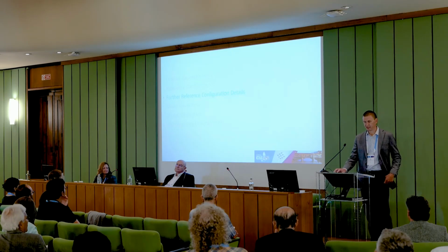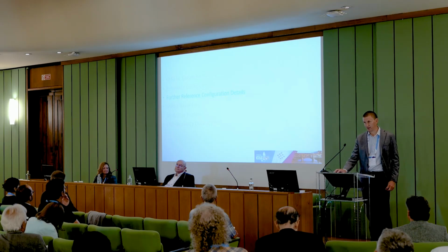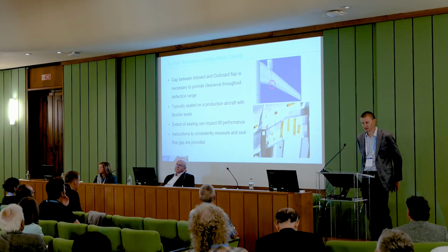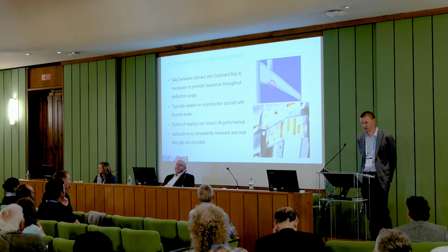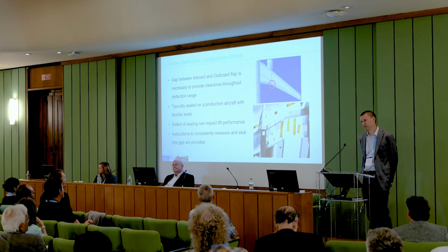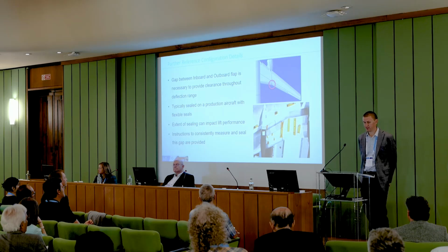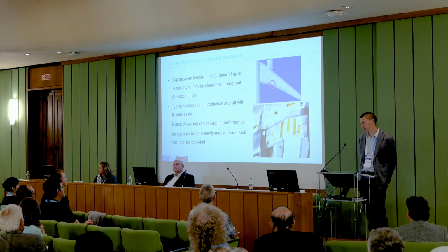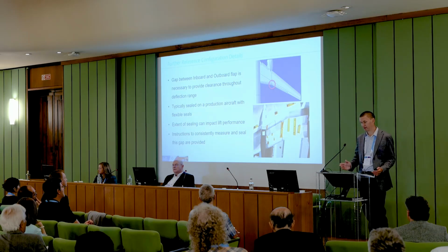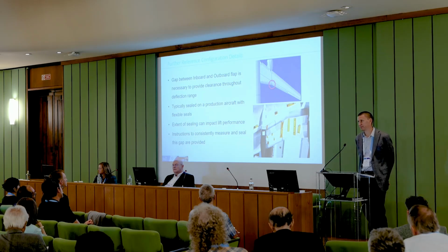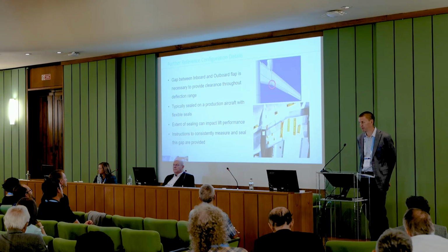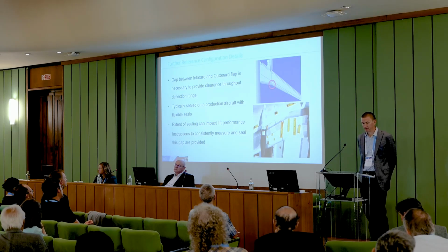A few of the further details that we found are important in our testing. So the first little bit is this gap that exists between the flaps. So the flaps themselves, we provide as full span lofts, not quite full span, but larger span than they typically would be. From there, they get trimmed, cut back from each other and from the side of body and from the end plane, such that they can achieve all of the deflection ranges that are defined.